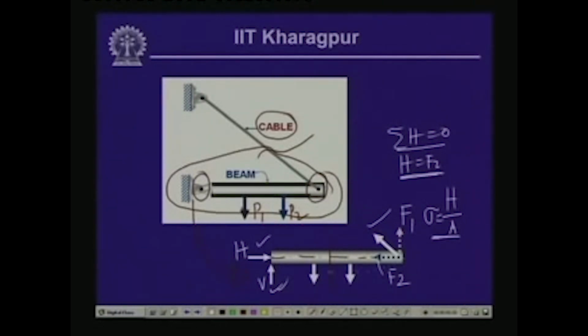Now, apart from that, since this particular beam is acting with these supports, the vertical reaction here and the vertical component of this particular force are also going to hold this particular point. So, the whole member will undergo a deflection because of this load, and there will be bending moment and shear force developed in this beam. Because of the bending and the shear there will be bending stresses, and bending stress, as you know, is again a normal stress which will be acting in the section in terms of compression and tension.